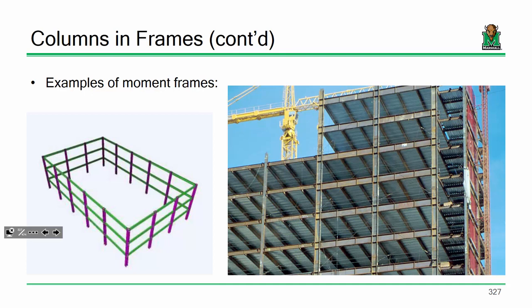Because think about it like this. More members holding up the building means that each member can be a little smaller, right? But if I've got more moment frame members, that means I've got more connections that I've got to make and more welding that I've got to do. So it's a trade-off, and it just comes with experience and time. There's not really a better answer than that. Did that kind of answer your question?